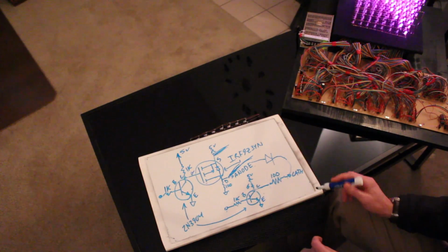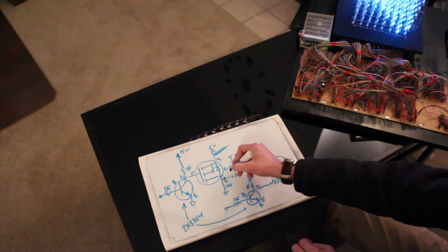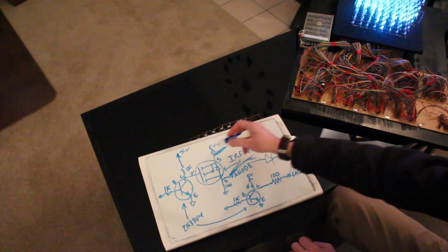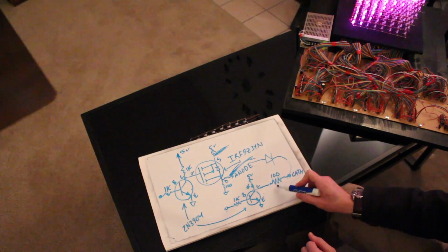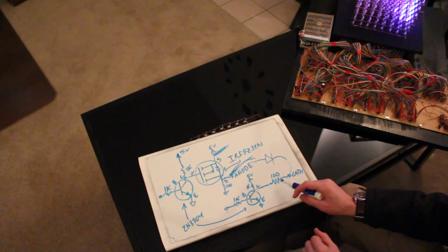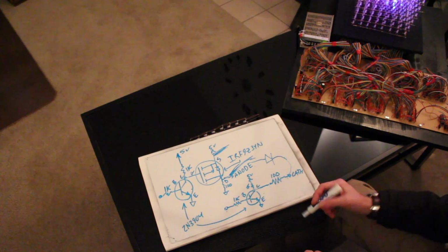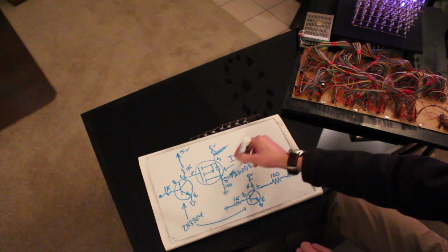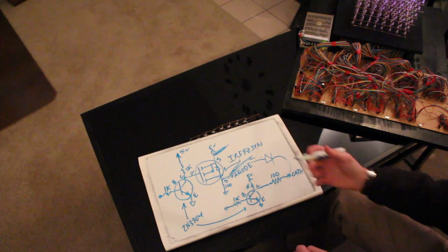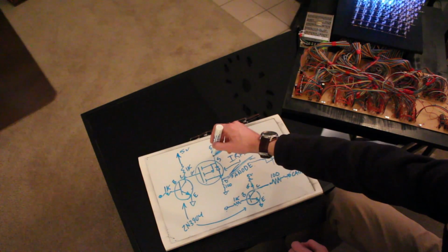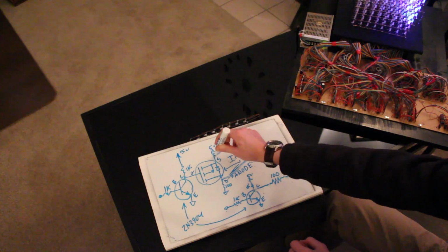Now I was talking a little bit about current. For each one of these outputs here, it's lighting up an entire level. This was calculated to be about 30 milliamps. So you take that 30 milliamps times 192, and that's what you need to source through this guy. Okay, which is a ton of current also on your 5-volt supply here. You're really yanking hard on it.